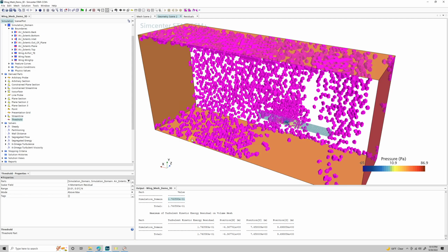So if you ever get one of those errors, that implies that something's probably wrong with your mesh. Or if you, again, get a value that's so far out of the realm of plausibility that it's just certifiably insane as a physical quantity, so it has to be a computational issue. Something like, hey, our flow velocity came in at 50 meters per second, and it's making it to 1,000 meters per second somewhere. That could very well be a sign that you've got a problem in the mesh somewhere. Because you know that just shouldn't happen under pretty much any circumstances.